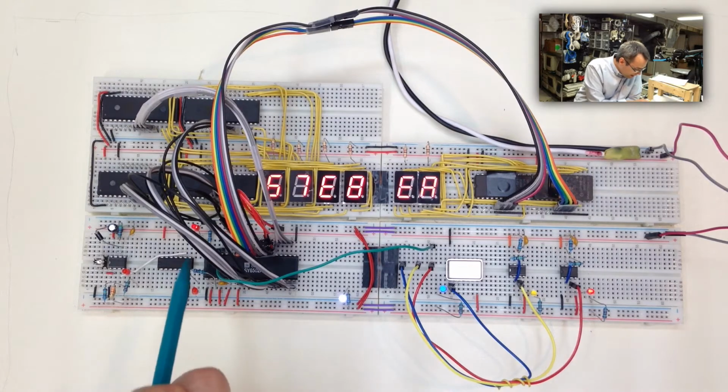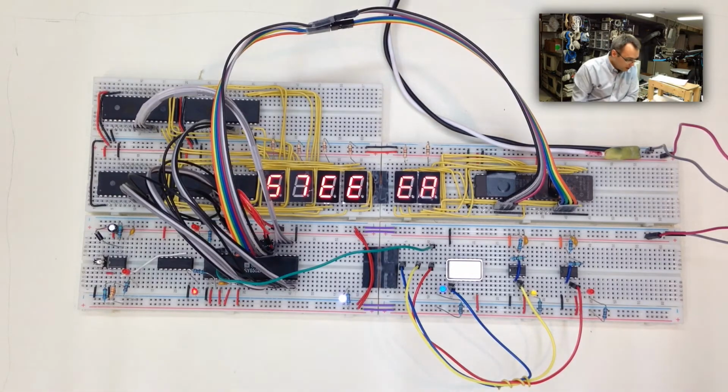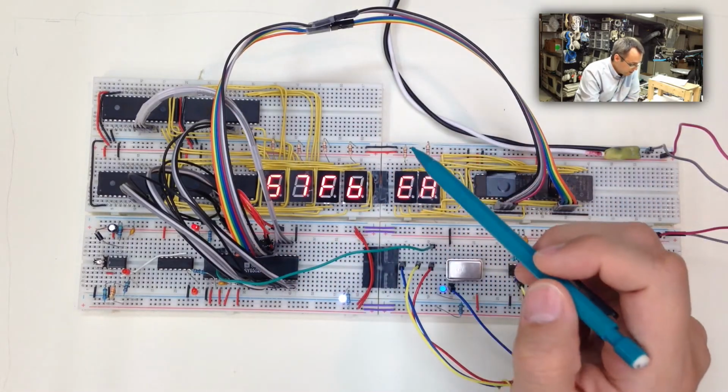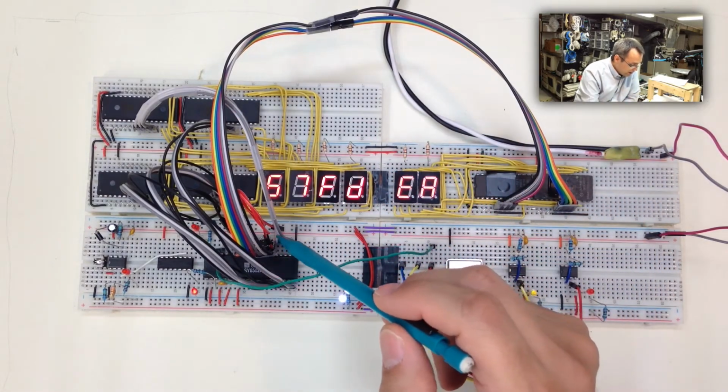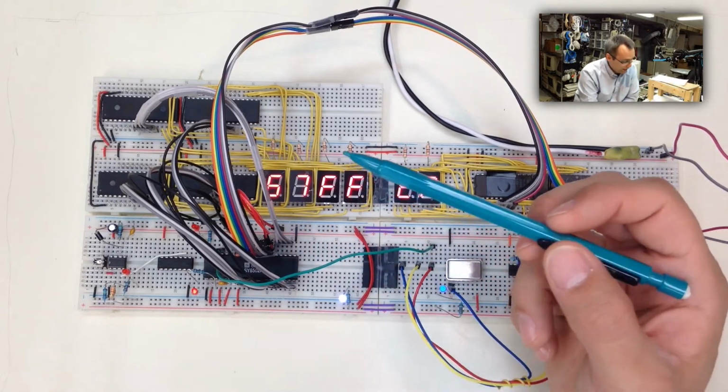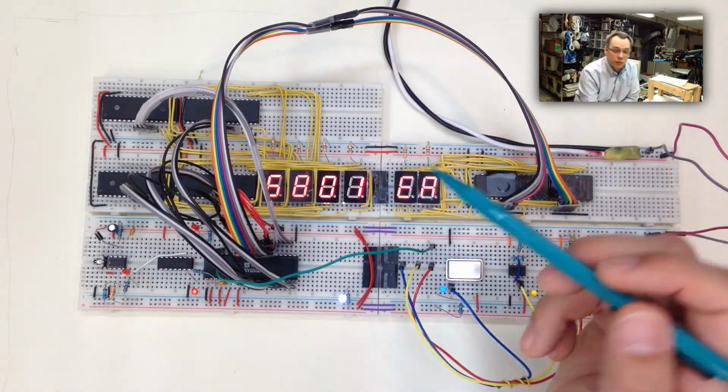And stare at our blinking lights and watch them blink back and forth for a while. That's neat. Well, we have the base core of the computer up and running. We have the 6502 wired up with the correct configuration to be able to output what's on the data in the address bus and be in a mode that we could potentially, as a next step, start hooking some memory into it, see what that does.